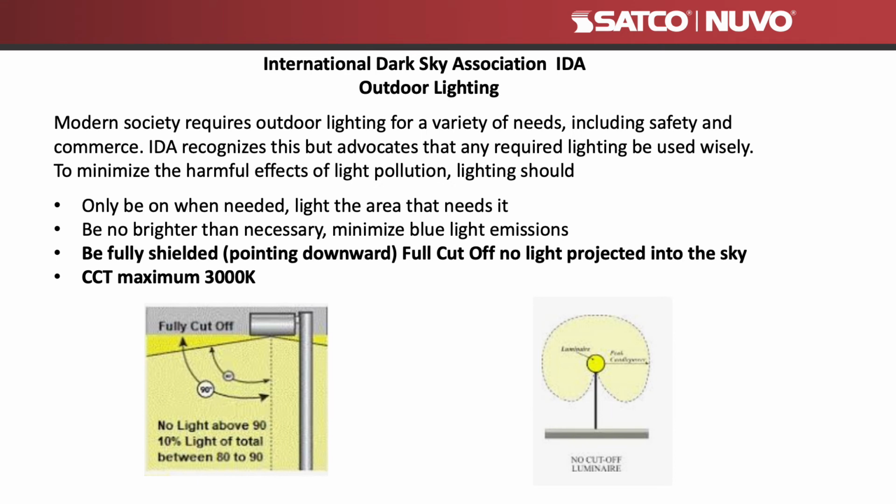When doing exterior lighting, you should be aware of any municipal codes that require fixtures to be shielded or have full cutoff. Full cutoff means that none of the light from the fixture escapes and goes into the night sky. Let's look at the fixture at the lower right. Here is a fully unshielded fixture which allows the light to go out in all directions.